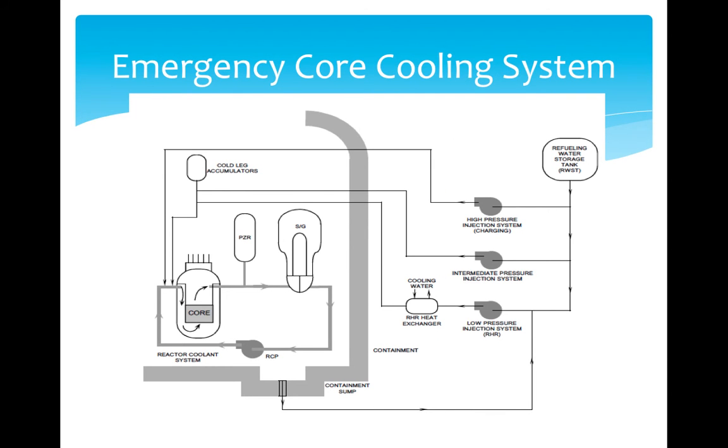An emergency core cooling system is installed as a protective feature. There are two main purposes of the emergency core cooling system. The first is to provide core cooling to minimize fuel damage following a loss of coolant accident. This is accomplished by the injection of a large amount of cool, borated water into the reactor coolant system. The second is to provide extra neutron poisons to ensure the reactor remains shut down following the cooldown associated with a main steam line rupture, which is accomplished by the use of the same borated water source. The combination of these systems, along with safe operation, are what make a pressurized water reactor the most useful type of reactor that is used today.